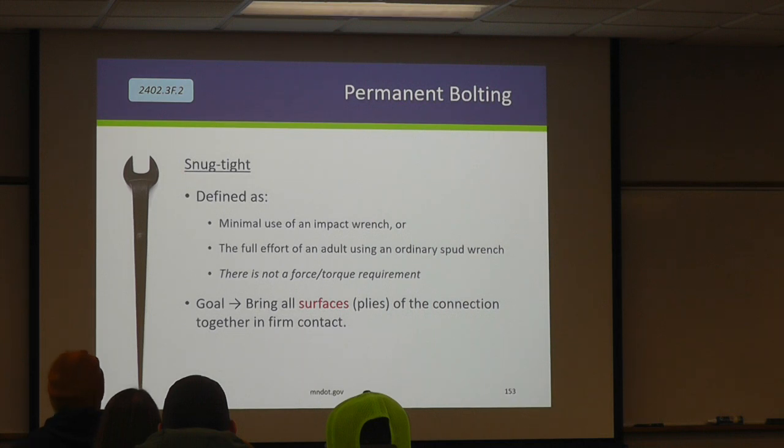So again, snug tight, the full effort of an adult using a spud wrench. We do, I guess we still say in there, minimal use of an impact wrench. It's not a torque force requirement. It's defined very loosely. I work on some national committees, and we still can't figure out how to define stuff. That just FYI. But really the goal is, when you think about it, if you want to bring everything into non-conflict, if you think about it that way, it makes a little bit more sense.